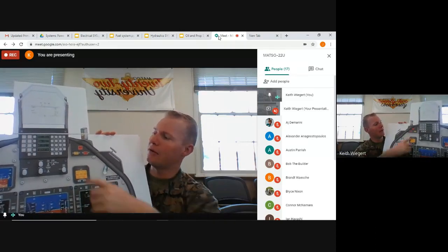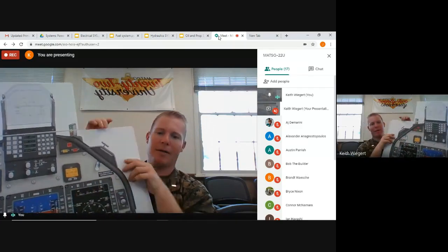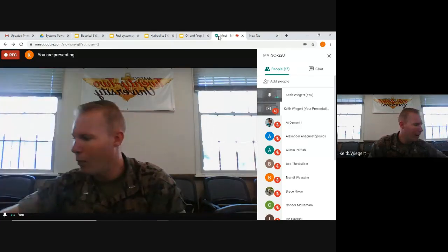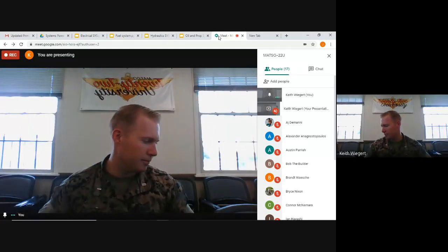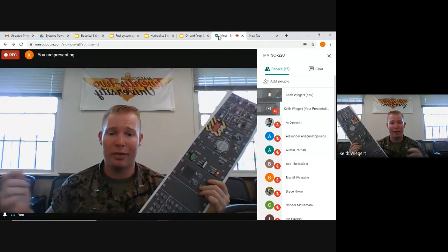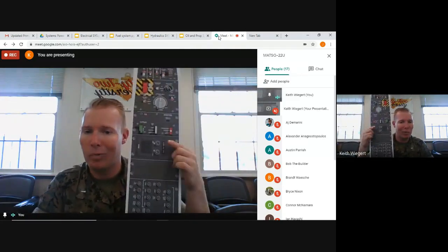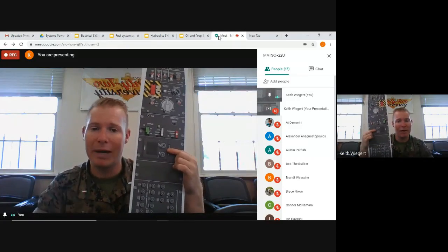So that is your UHF and your VHF radio, right? We've got our standby VHF control head. Now, whenever we lose power, we're not going to have the upfront control panel, so we're not going to be able to control things up there. Instead, we've got the standby VHF control head over here, which is going to use the same VHF radio.